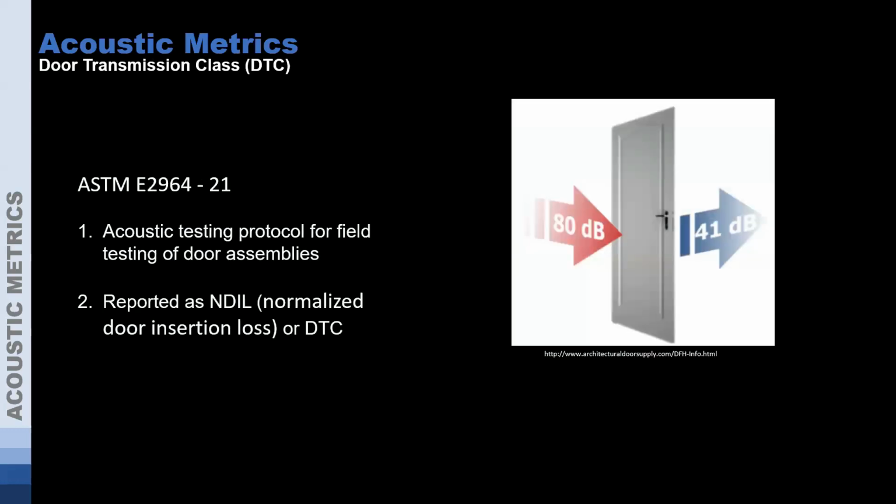And then DTC, your door transmission class. This one's not as common, but still sometimes needs to be looked at. It's going to be more of a field test to see how much sound is actually reduced by a door, and this isn't looking at the door and the wall and the whole area. You may do an STC test that has a door in a wall, or a field test that has an NIC.